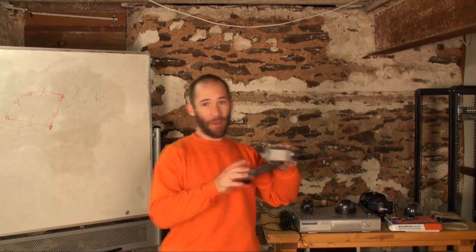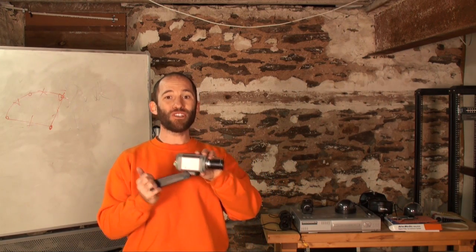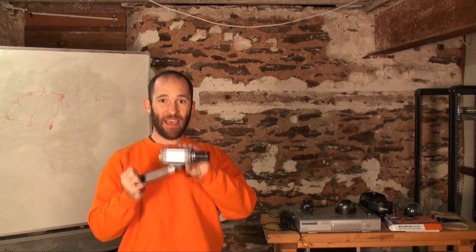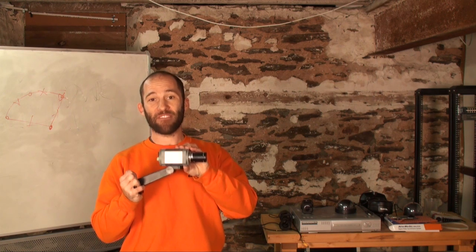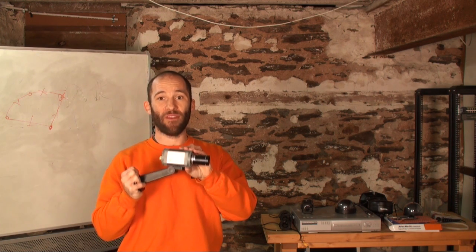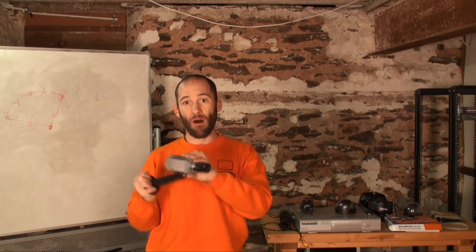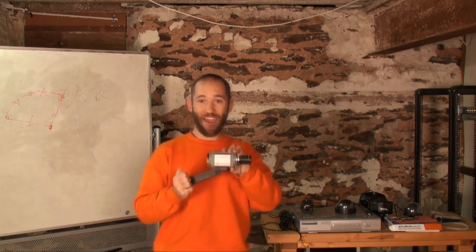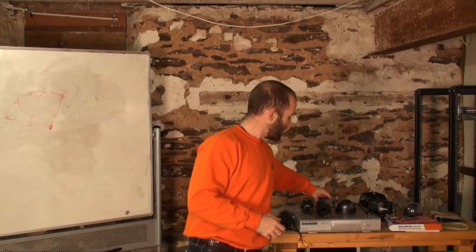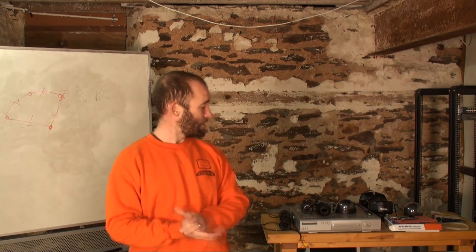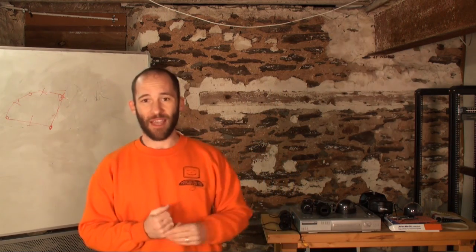These 5 megapixel cameras push out a lot of data. If this is pushing back to an FTP server or back to a network video recorder, and you have 10 of these on your internal network, you can bring your internal network to a halt if they are all sending back 5 megapixel video. I forget exactly how many megabits per second that takes up.